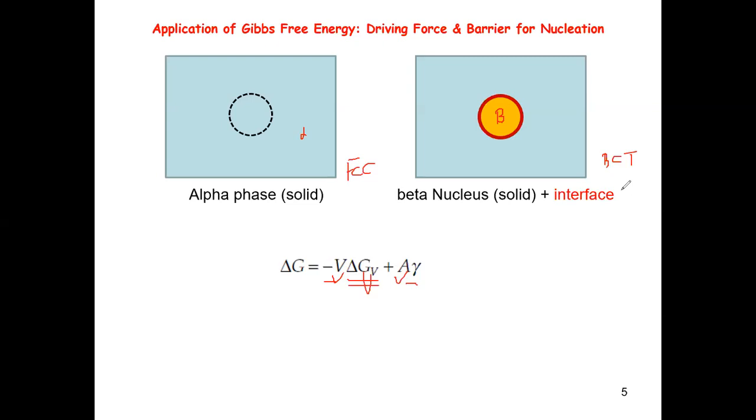Now you may ask, why don't we have to consider this volume change in the solidification process? Because in general, we know when water freezes into ice, the volume changes. Well, the reason is that water is a fluid. If you have a small solid inserted into the water, it won't play any role, because the total volume of the water just expands a little bit and occupies a little more of the container, because it's a liquid. But this is different for the solid, because the solid cannot flow. It cannot easily adapt its shape and total volume in response to a change of volume in a small region.